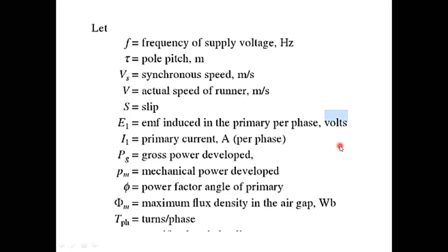Even in the linear induction motor, we are getting harmonics. That is also very important. Therefore, to reduce the harmonic values, here we are interlinking the core by using a steel secondary core back.